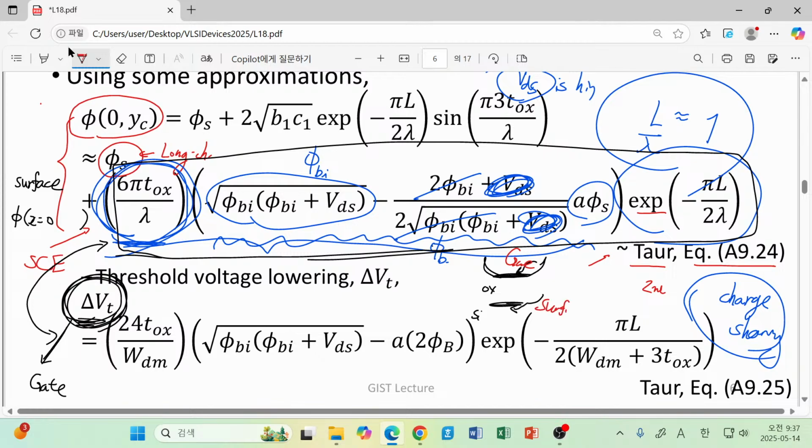Of course, there is a conversion rule between our gate voltage and surface potential. What was it? The change of gate potential is introduced as a change of surface potential, and there was a conversion rule for these small deviations. That was just a number m. Simply speaking, if we change VGS a little bit, then there is a factor of 1 over m to convert it to the change of surface potential.